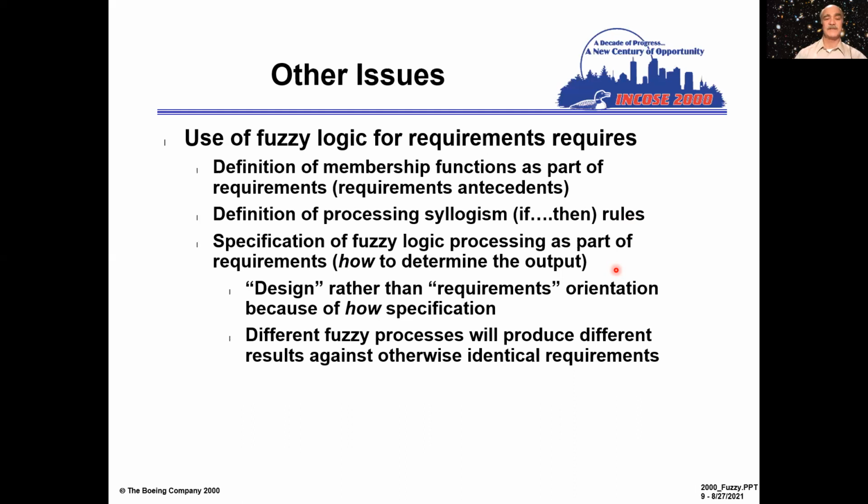So for example, in transistor logic, you stay at 0 until you hit 2, or you stay at 1 until you hit 0.7. So it's a hysteresis kind of description. And then that covers that no man's land between 0.7 and 2, because you don't make a state change until and unless there's an actual transition across the boundary.